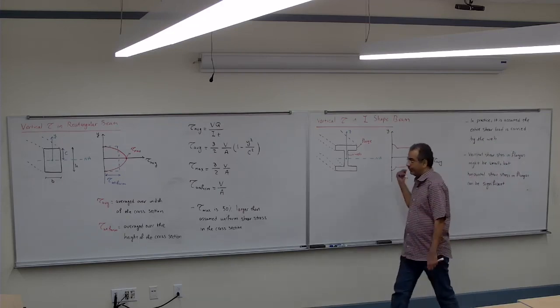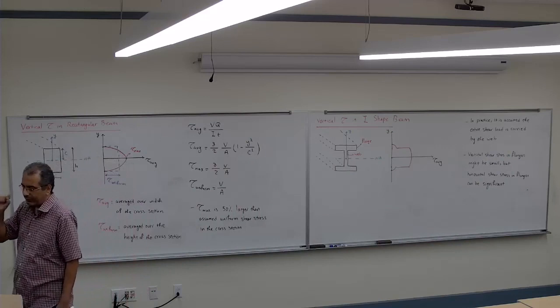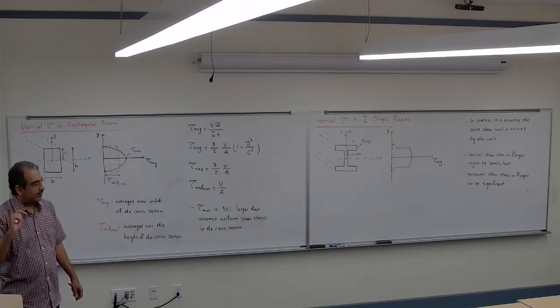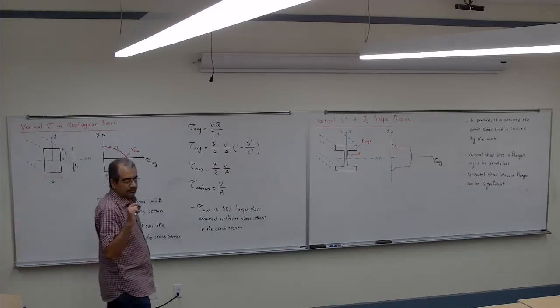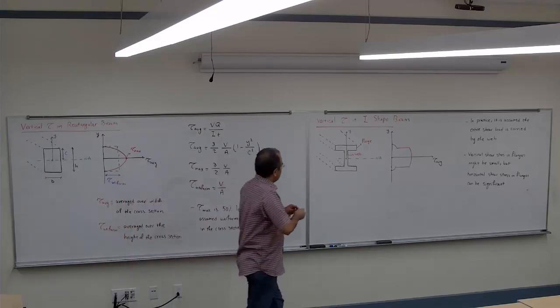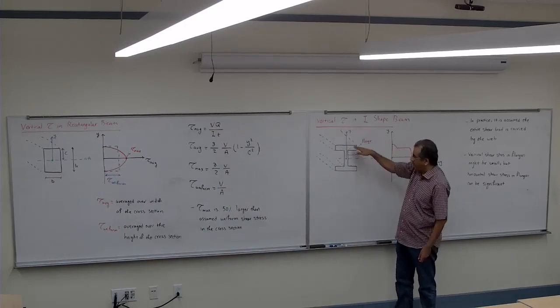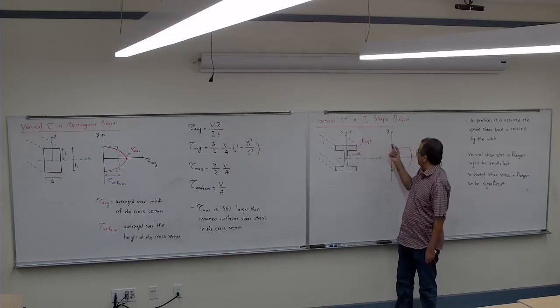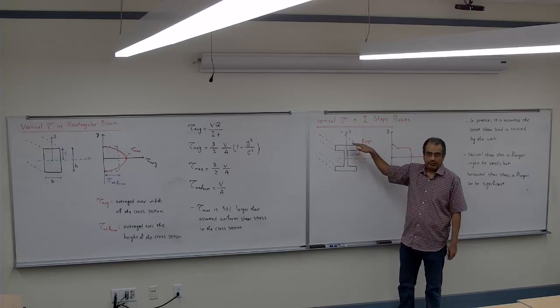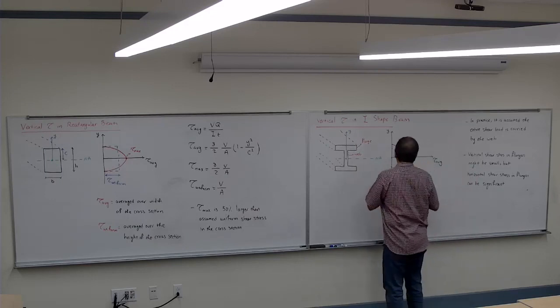So remember that what I'm talking about, that is small in the flanges, is the vertical one. Look at here, the shear stress at the flanges is going to be vertical and horizontal. The vertical is very small. The horizontal might be really big. So don't get confused.